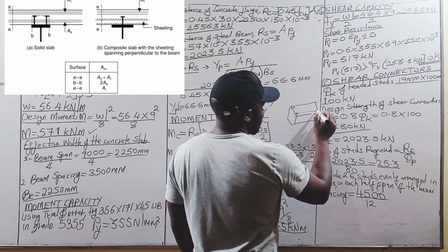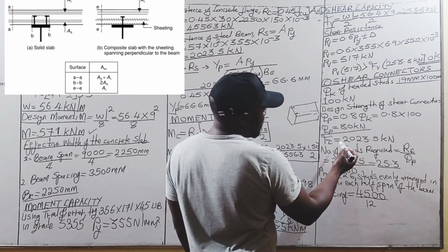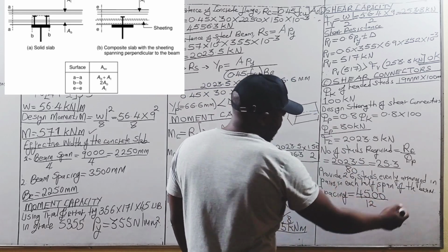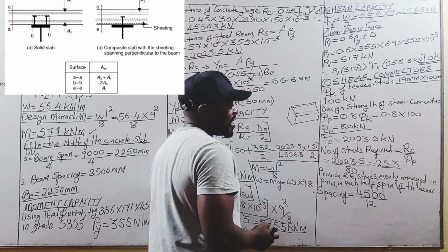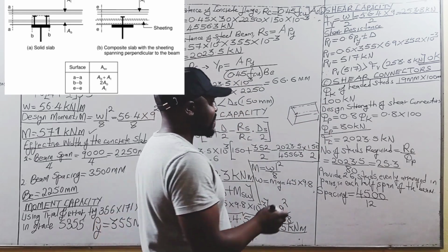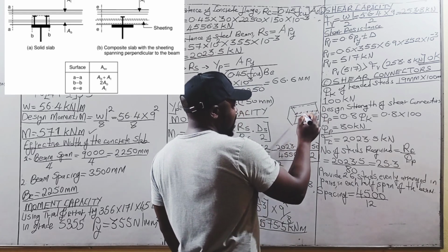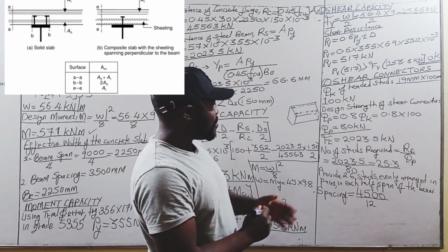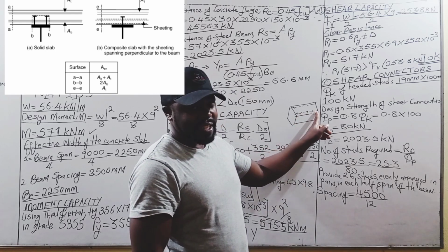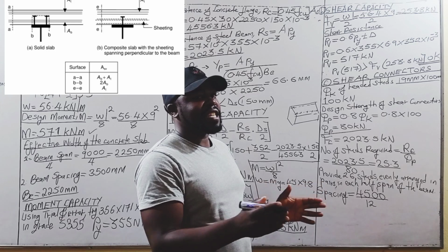Therefore, this side we are going to have 13. That is a half span of the beam, and the other side we are going to have 13. Now, for us to get the spacing, if we have 13 studs, we are going to divide by 12 because in the 13 studs, we have 12 spaces in between them.